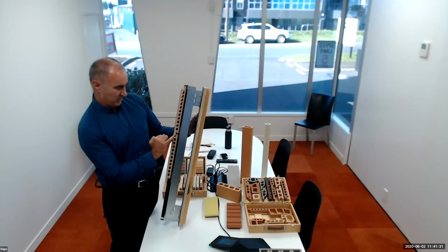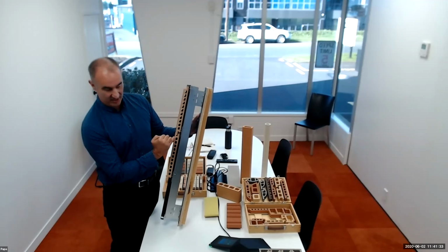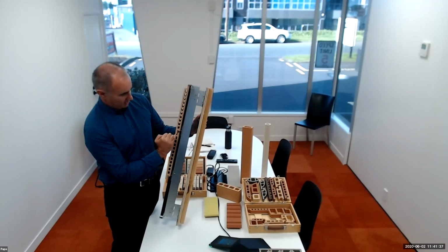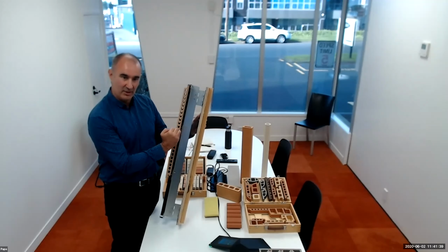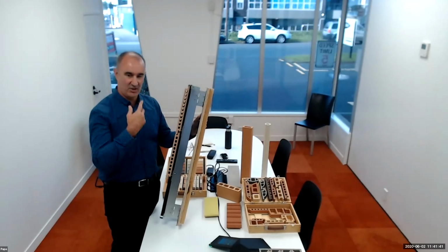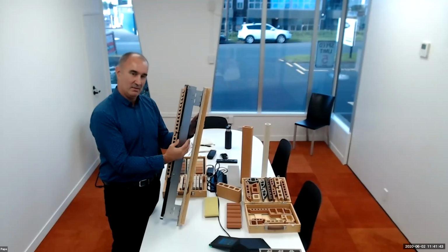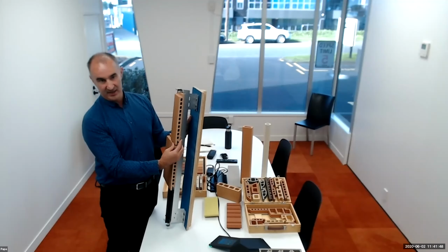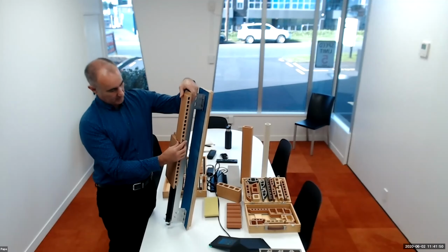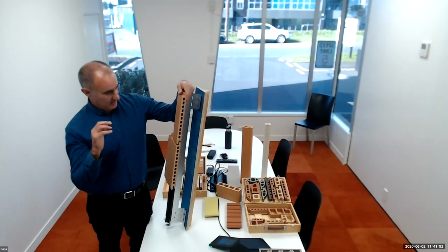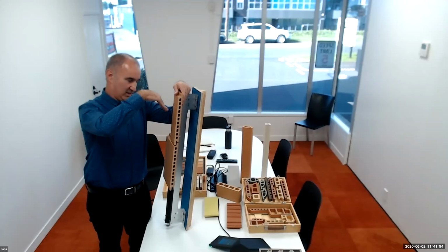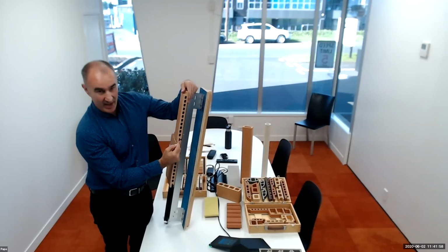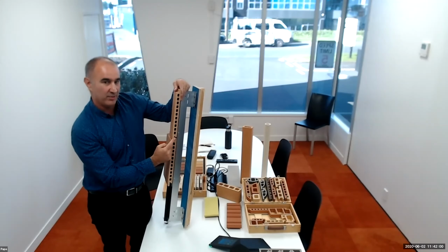But you've got this open joint here. It is a labyrinth. It's like a shiplap, kind of like your weatherboard type thing. But there is a gap that will allow air in through here. So that's constantly ventilating the space in behind. Now you probably think, okay, well, water can get in there too. Yes, it can. But when you think either rain coming this way or even horizontally, it's got to work its way up and around this labyrinth.